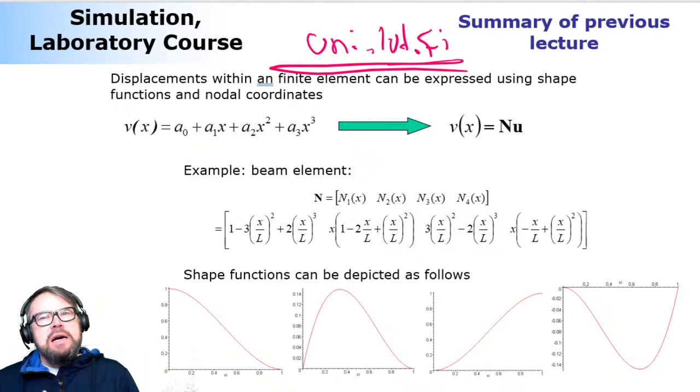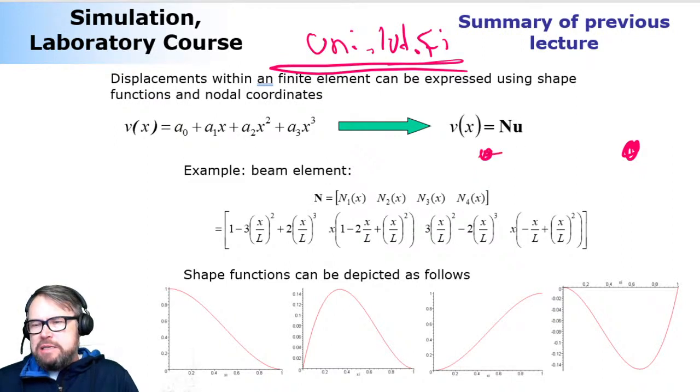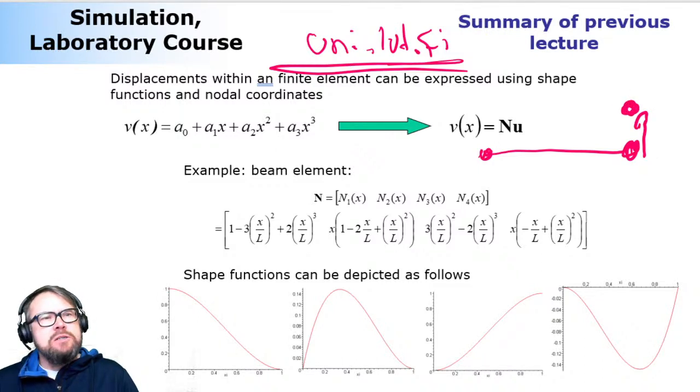And the way that the behavior is materialized, or how it is actually expressed, is in terms of nodal degrees of freedom. So if you have, say, an element with two nodes, and this is obviously a beam-like element, there's a line that connects these two nodal locations. Now, if you introduce a displacement in this direction, obviously this nodal location is going to move here. So it's all about how the particles between these nodes behave.